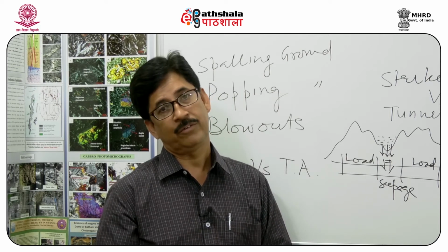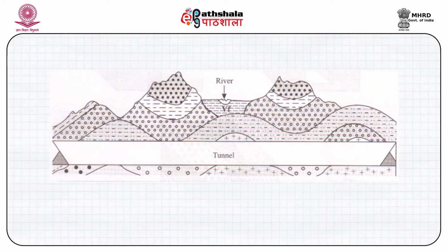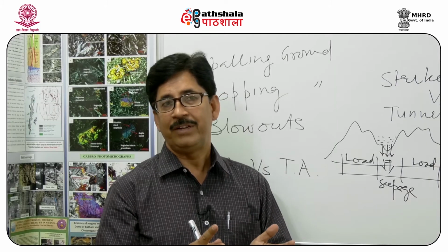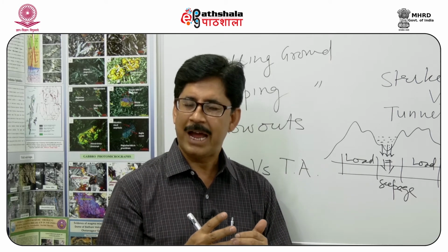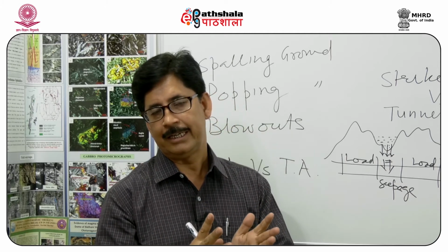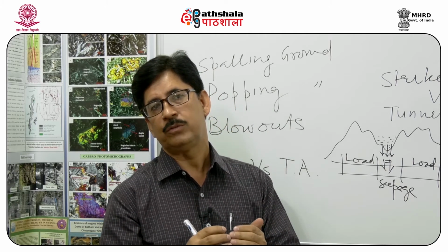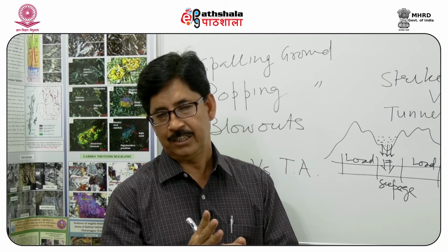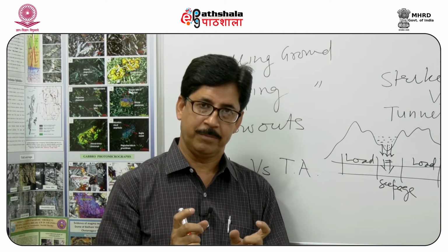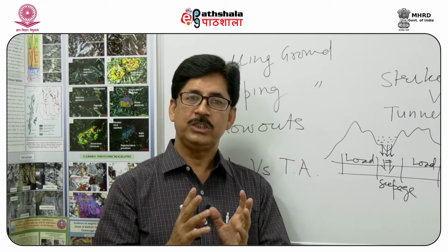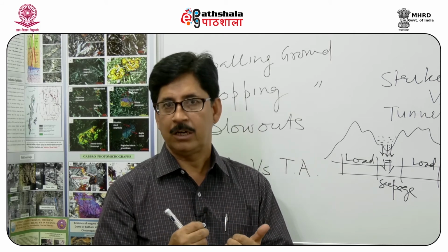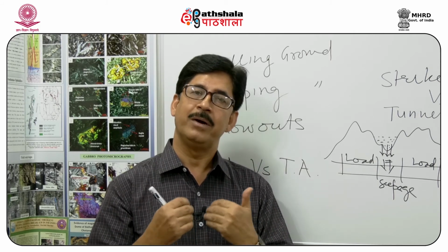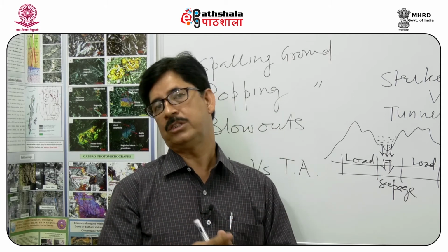the fault we have a lot of crushed rocks. So the seepage problem may be there. If we have to have our tunnel through the faults, then we should take those faults at 90 degrees so that we can have a minimum of them. And the rocks which are present as crushed rock, crushed zone, that has to be excavated out and it has to be backfilled by concrete or reinforced concrete.